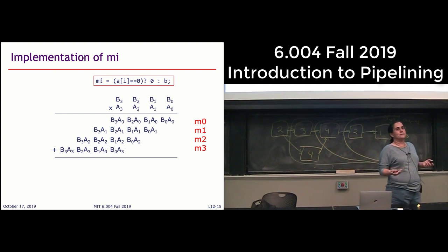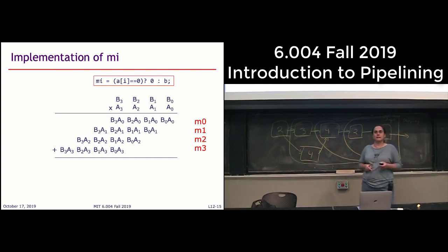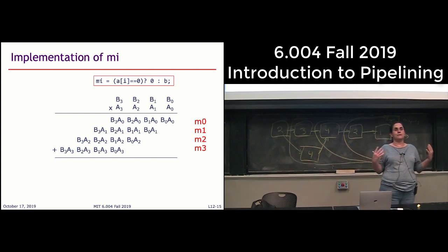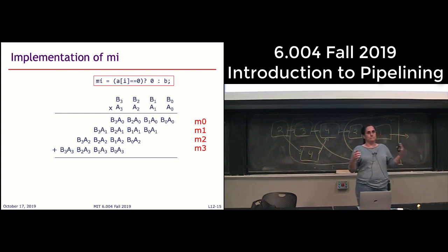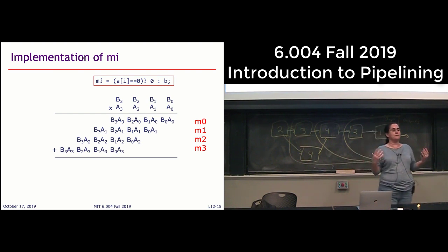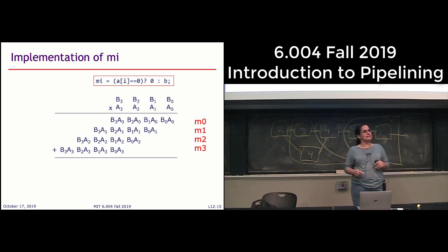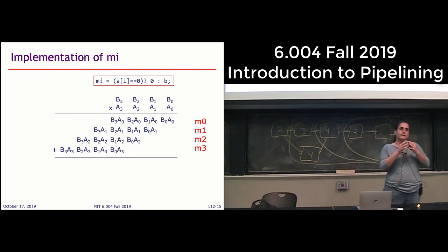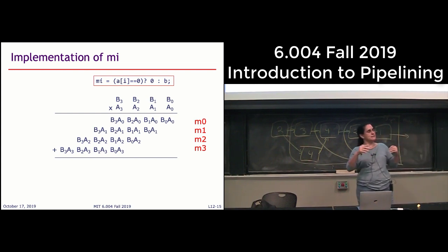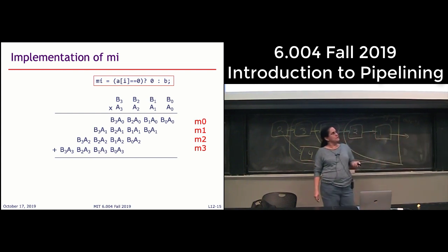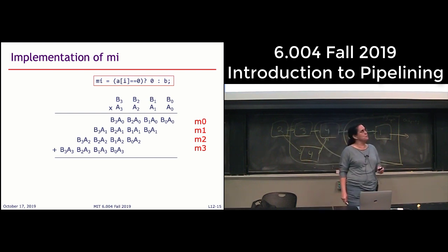So in the previous slide, we saw that we could implement it as a multiplexer. But it turns out that you can actually use much more simple circuitry than a multiplexer. Because remember, multiplexers are very expensive, right? If I have a 32-bit multiplexer, if I think about how many 2-input multiplexers it consists of, there's at least log n of them, basically a tree of multiplexers to produce this 32-bit multiplexer. So it would be nice if we could do something much more simple.